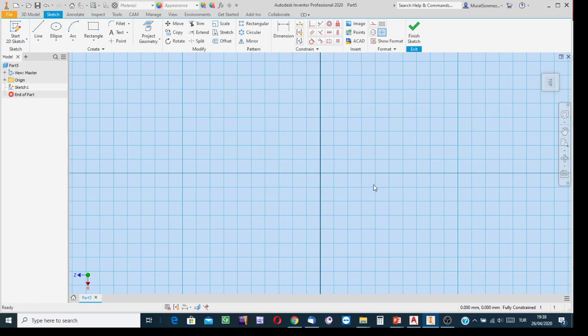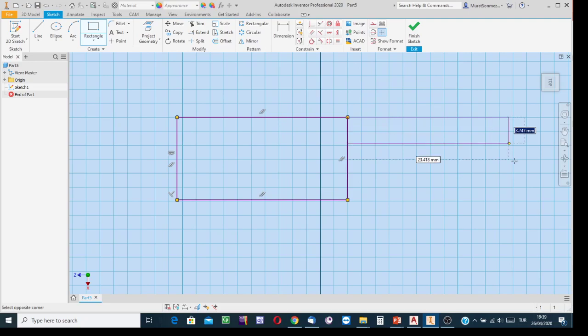And in sketch mode, schematically draw the truss. In doing this, just consider that the lines are passing through the centroids of the cross sections of the members. There will be, in this example, 2 full cells. Instead of drawing the schematic of the cell line by line, I know the boundaries form a rectangle, so I select the rectangle creation button to save time. Create a rectangle arbitrarily, and then snap to this corner, and create one more rectangle arbitrarily.